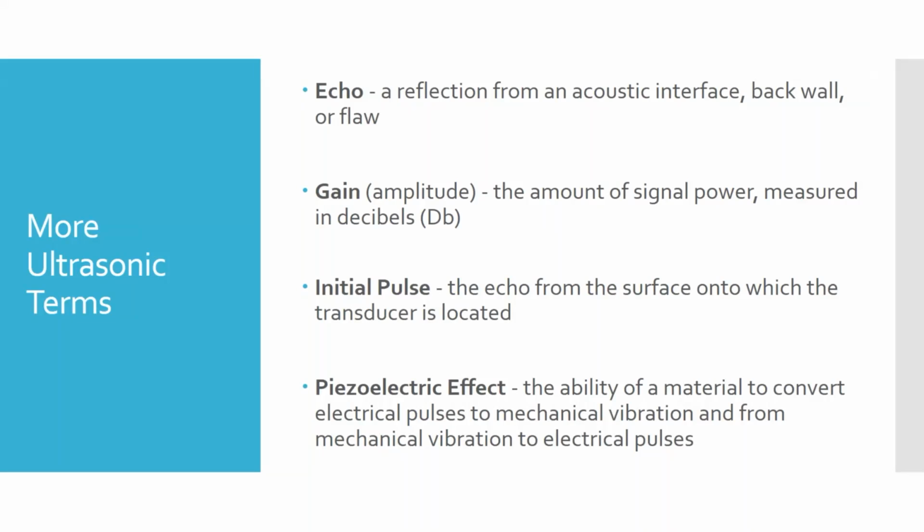Okay. Our through transmission probes, the one in my hand here, they're kind of medium sized. No, where are we? Actually, I didn't bring one with me. I didn't bring the through transmission probes. We've got two pairs of them, two sets of them. And so you hold them across from each other and you look for the sound to make its way through. So you're not looking for an echo in that case, you're looking for the direct transmission of sound.